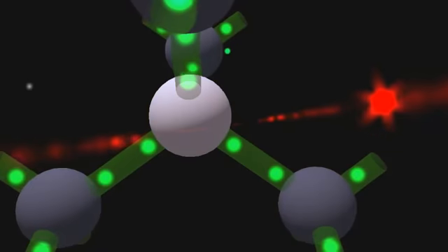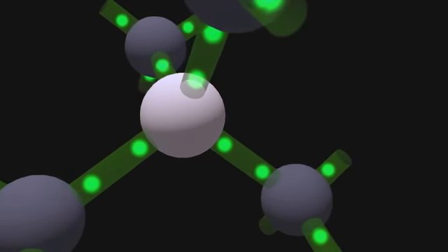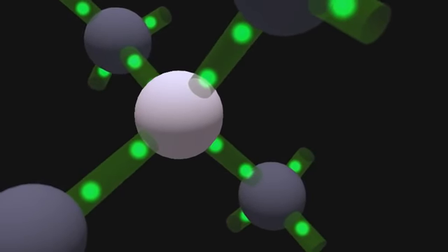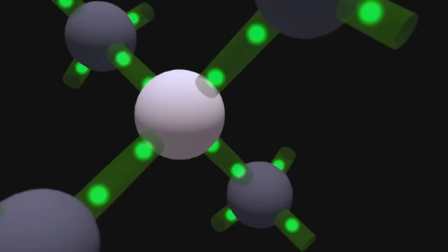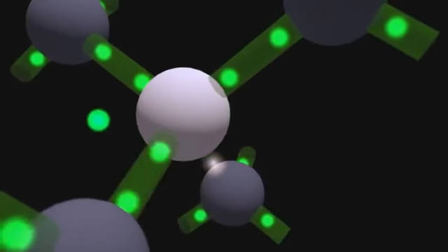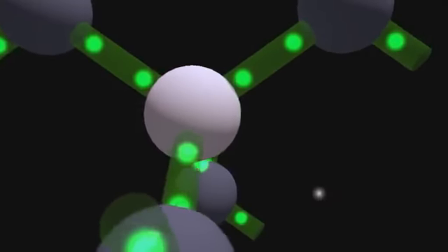In the case of certain materials, and under forward bias, this energy is emitted as light. The more electron-hole pairs recombine, the more intense this light is. The operation of the photodiodes and solar cells is based on the opposite physical phenomenon, generation. Thus, a photon can create an electron-hole pair, which by its movement can generate an electric current.